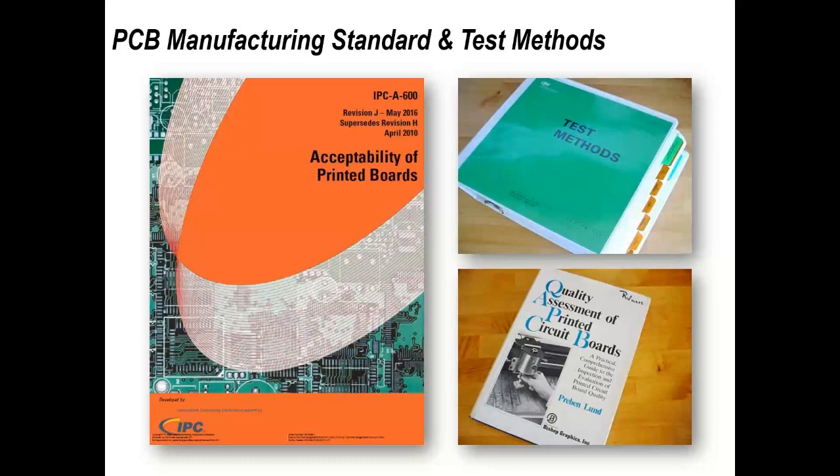And you will have defined what you want, and within that document there will be basic optical visual criteria based on that. The test methods manual is a manual, as its name suggests, but it's all of the test methods that are covered or included in documents within IPC. So there's a test method for pretty much anything, but there's specifically one on microsectioning.